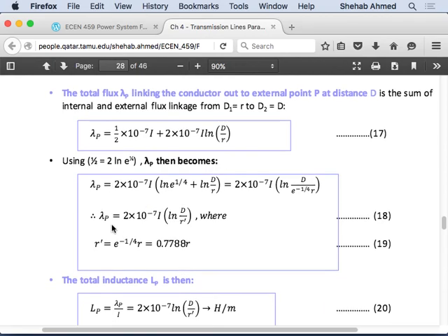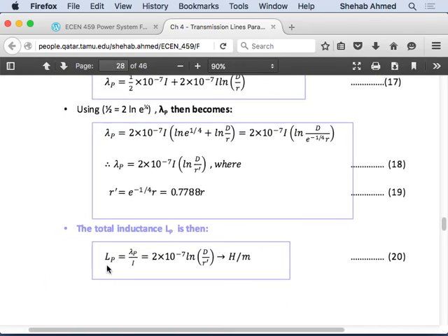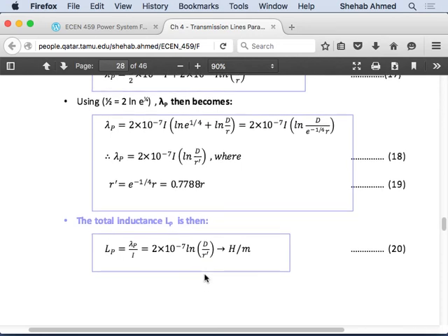So we rewrote this. And then if I would like to find my inductance, it's the flux linkage divided by the current. Which current? The current that created that flux linkage, right? Because now we did it for this one conductor. But now we will bring in another conductor, and we will have current flowing through that, affecting flux linkage in the vicinity of the first conductor. So is everybody okay with this until here? Yes, no? I can repeat it quickly if you...